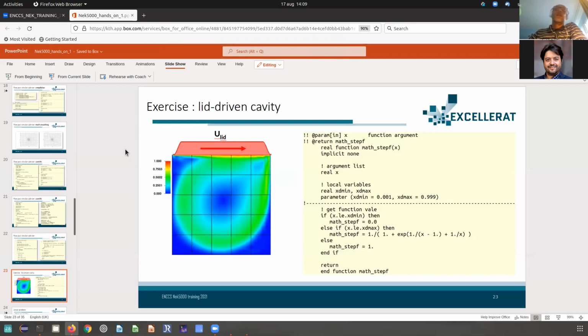So, for instance, going from Dirichlet to stress-free or something, you have to do a lot of initialization again, which is maybe easier to just restart. Everything has to be reinitialized because the boundary condition influences the pressure preconditioner. So the whole pressure preconditioner would need to be restarted as well.